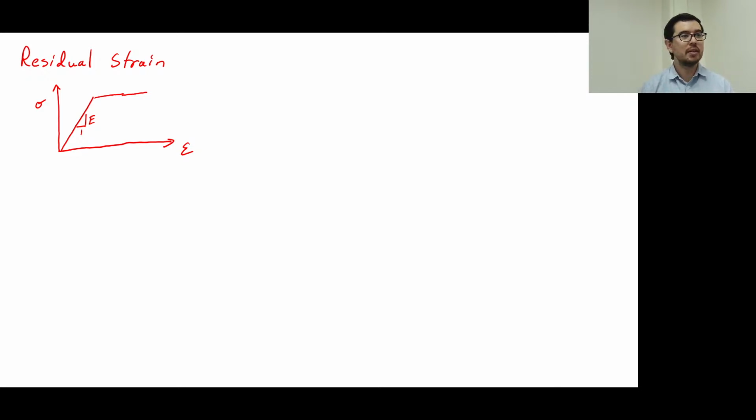Yes, Dylan. The elastic limit. Okay, so the elastic limit, which I said we're not going to think about too much, although it will come up in a minute, or the proportional limit and elastic, and we'll talk about them. But what do we use instead usually? We say that it's all lumped together. Yield strength. Yeah, the yield strength is usually what your material providers are going to provide, or you're going to specify.